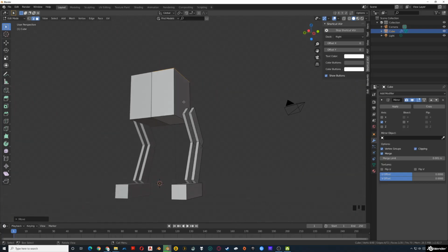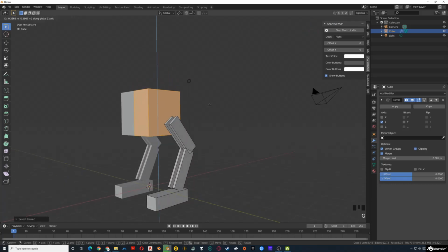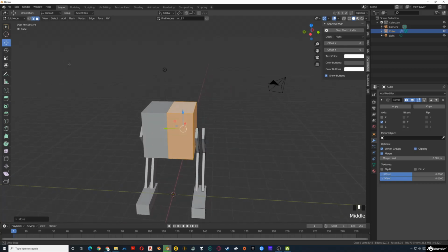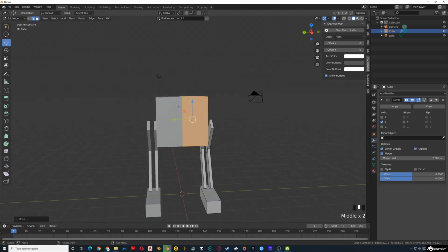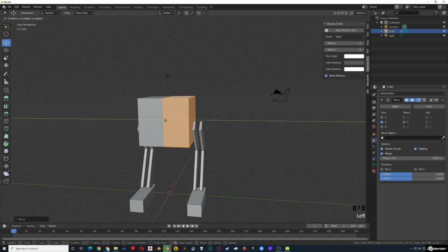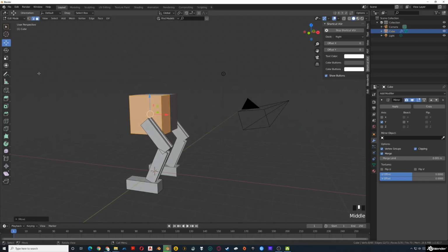I actually think I might want to move the whole thing down a little bit. So I'm going to hit L and then G. I always hit G when I move or grab. You can also, if you wanted to, use this move tool, gizmo they call it, and that'll give you the old cursor if you're used to that from the old version. Otherwise, I'm just going to leave it on regular selection mode.